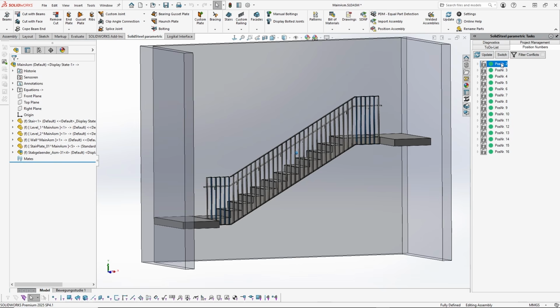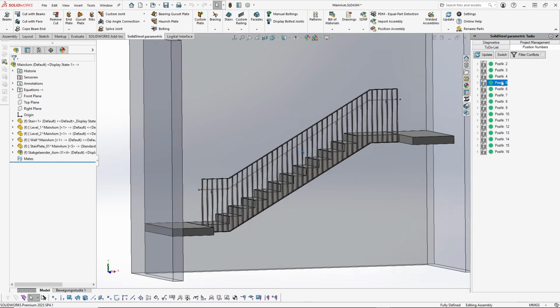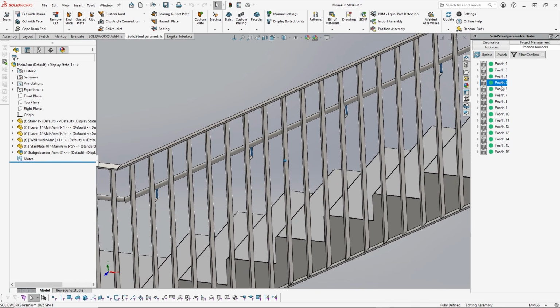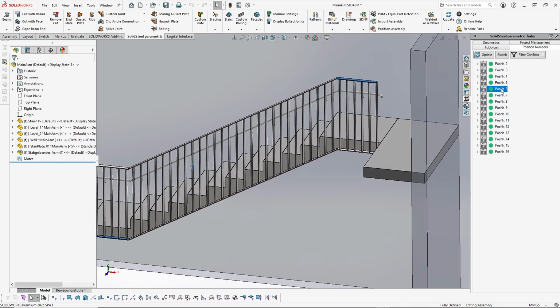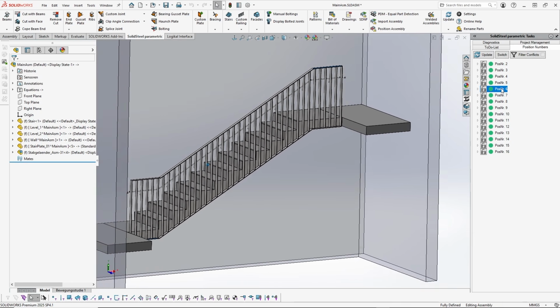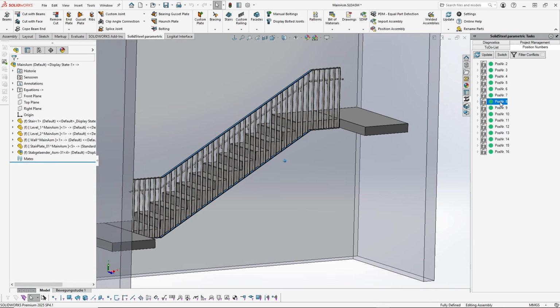Here we have the upper and lower vertical infill bars. Here are the short handrail segments at the top and bottom, and here the long segment. I don't immediately see position number 5. Let's check. Okay, these are the small vertical handrail brackets. These flat steel parts are diagonally symmetric, which is exactly what you would expect given the railing geometry. And this continues for all remaining position numbers across the entire railing. Position 12 refers to the bent segments, and position 13 already belongs to the staircase.